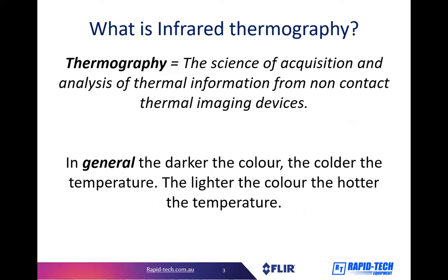The definition of thermography is capturing thermal information using a non-contact device, such as a thermal imager, and then performing some sort of analysis. In simple terms, a thermal imager, such as this, is made up of multiple pyrometers, which read infrared energy and convert this to a corresponding temperature value. In turn, this temperature value is represented by a color palette to give you a more visual display.